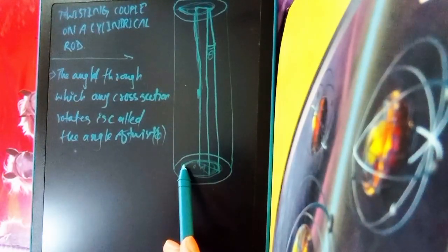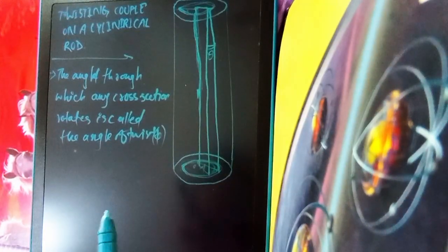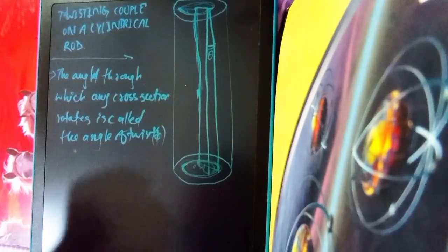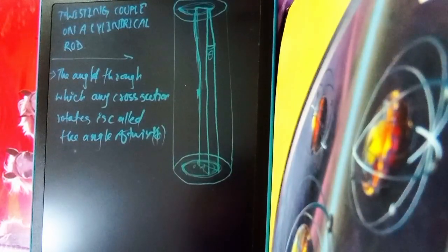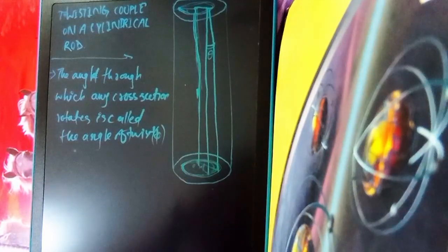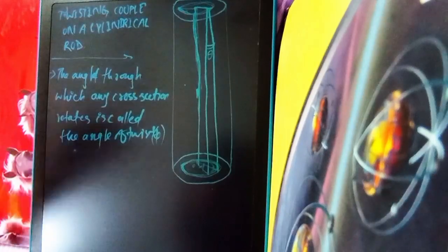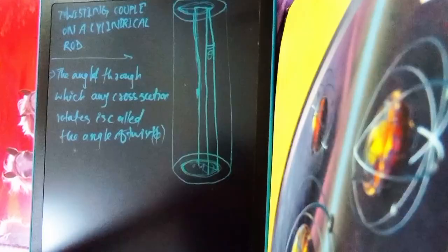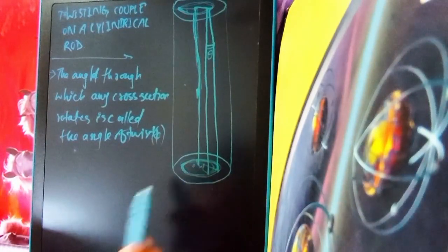Just imagine, when you put something like a rod or some material and twist it, its inner particles also get displaced. So we are imagining a small inner particle of the rod. Now we will imagine that the thickness of that coaxial cylindrical cell will be dx, and the radius of that cylindrical cell from its center, the axis, will be x.